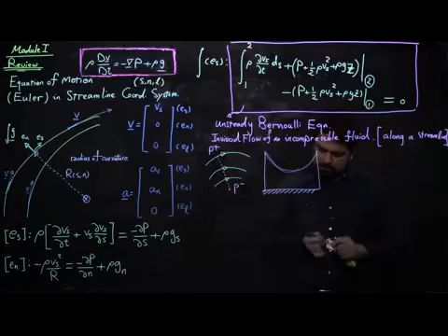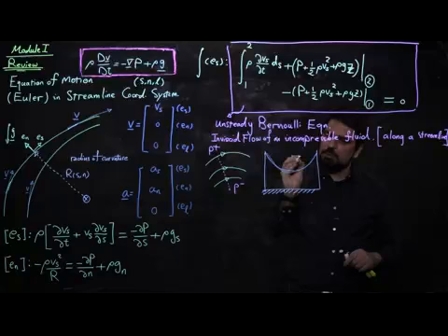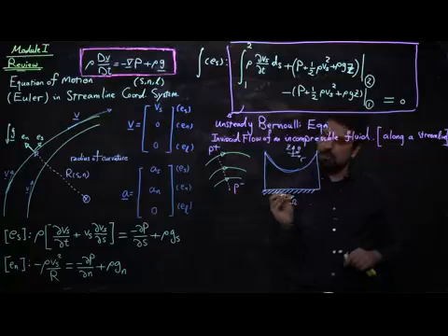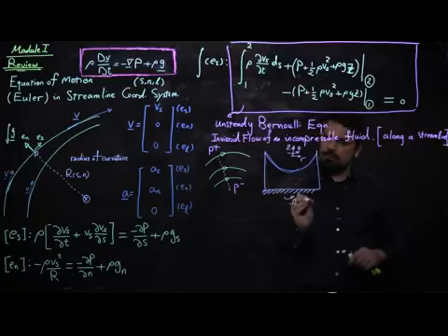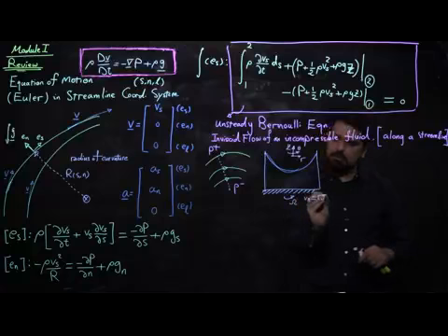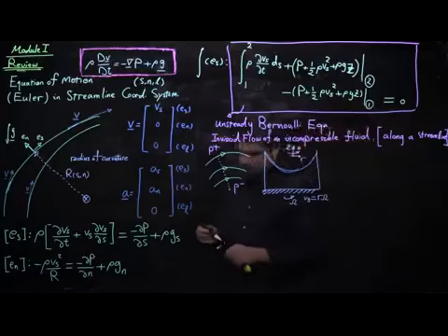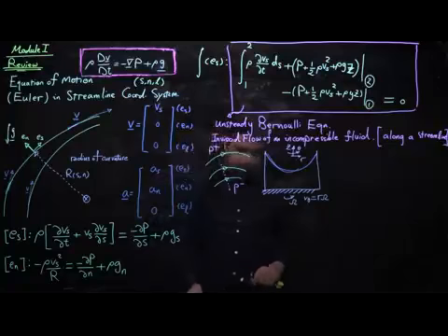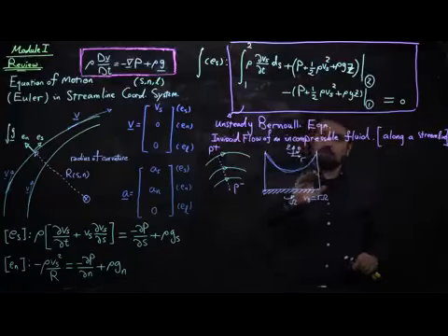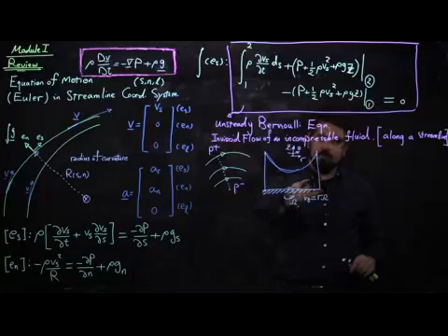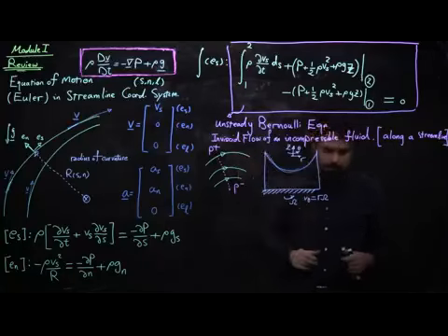So this is the classic example where you use the cylindrical coordinate system r, theta, z, and things are rotating in the theta direction with an angular velocity omega. So v theta turned out to be r times omega. And we notice that in this case, centripetal acceleration gives rise to higher pressure at points that are further away from the center, and that would give rise to an increased pressure that should be compensated by the rise of the liquid column on its top. That's why we get a parabolic profile.